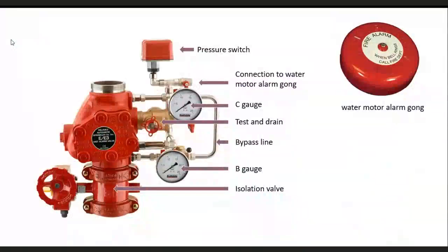So let's look at a bit more information about the equipment. This is an installation control valve. This one is a reliable brand one. Each manufacturer has a different style of doing it, but they've all gone through the same approval process. Although on approvals, that is something you have to look at. This valve here is LPCB approved, UL approved, FM listed, and VDS approved. So this one has all four major approvals, but some valves will just have one or two. That depends on what you want.